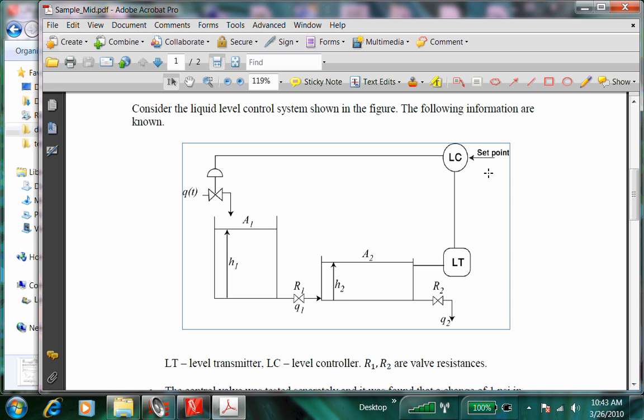Now, is there a disturbance variable that you could identify? R1 and R2 could be a disturbance? A disturbance is something that is not directly controlled by a controller, but you could upset the process by opening, for example, even Q2 could be considered as a disturbance variable, if you could just open up the tap, not thinking of the manual valve.